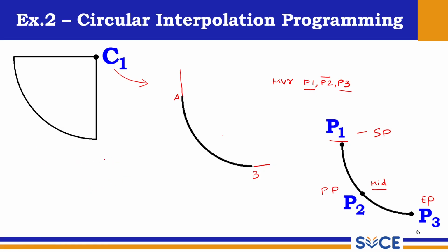See now, it is not only applicable for an arc, even you can use the same case for drawing the semicircle also. So there are 2 points, consider whichever point you wanted to have. So from here a semicircle comes. So this will be point P1, the starting point. So obviously this will be point P3, the end point, and here the mid should be the P2 passing point. So likewise you can go ahead with that.